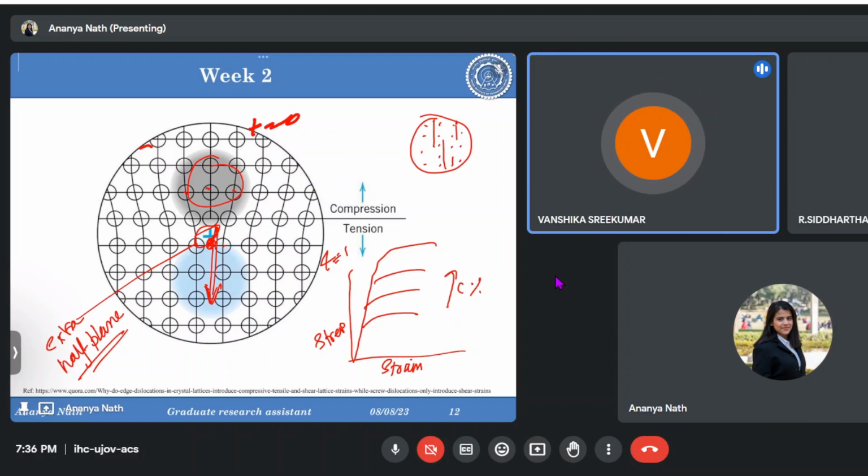Basically, in a stacking fault, you have another small lattice present inside a bigger lattice. So the dislocations can't move in that region where the stacking fault has occurred, and the larger the width of that stacking fault, the more difficult it becomes for them to travel faster. Yes.